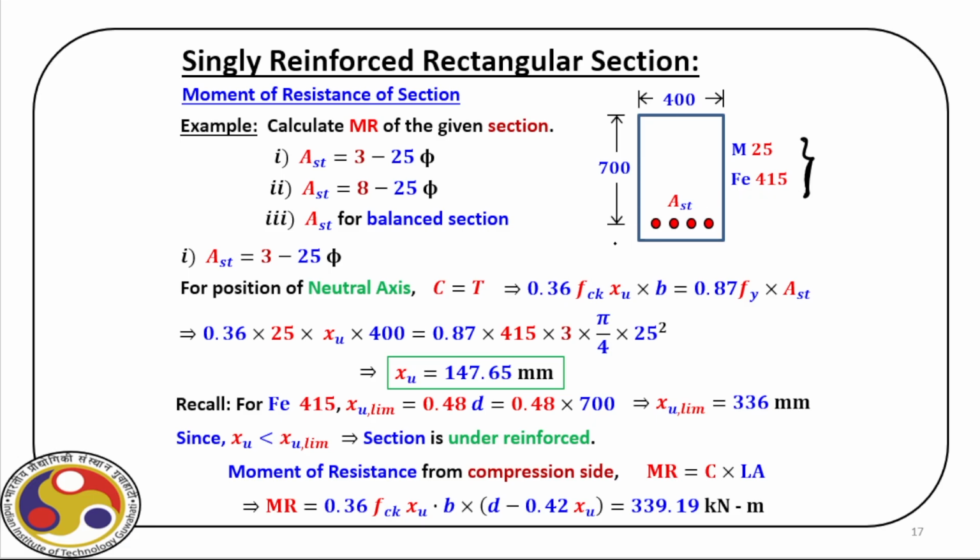Again, normally we go up to this point, that is the total depth, from where you have to figure out the effective depth. And I have already explained in the previous lecture that there are clear guidelines for the clear cover. Depending upon the situation, the type of exposure you have, and the grade of concrete, we have specific values of clear cover that you have to maintain. We can do that, but for the time being, our d effective is given, which is 700.